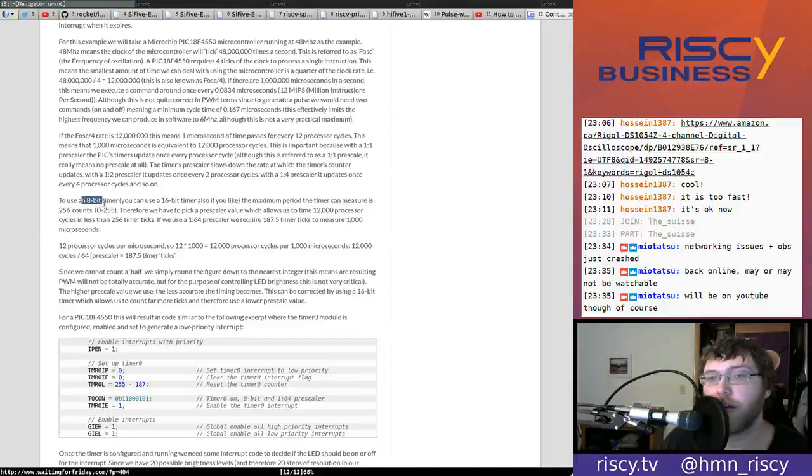And then they also point out that they're using an 8-bit timer. So, I mean, we're going to be using like a 32-bit timer, right? And we can run at like 256 megahertz or whatever. So we obviously have a lot more computational power at our disposal, but we also are messing with 3 different channels, not just one.